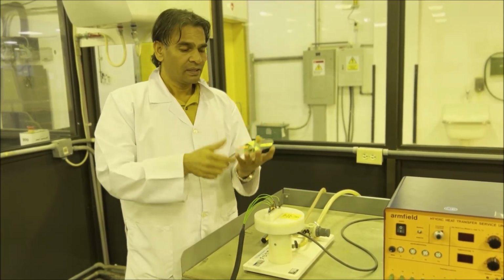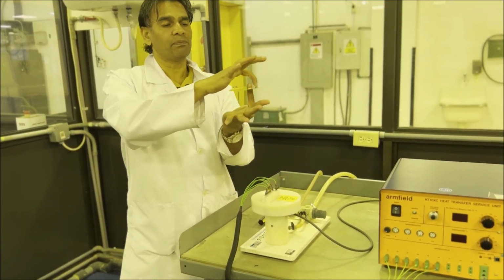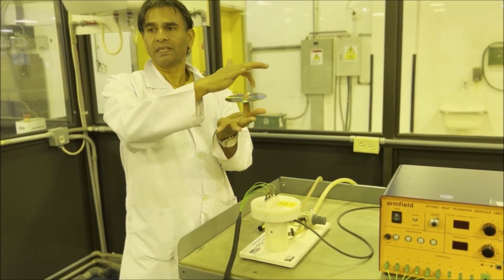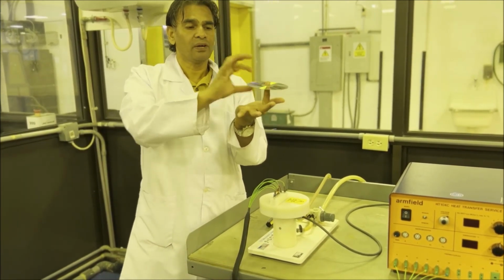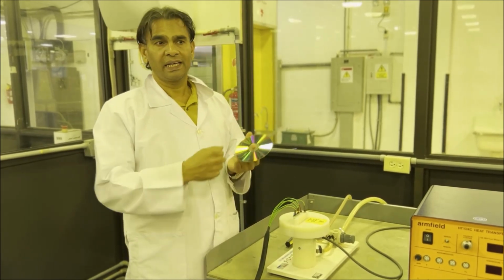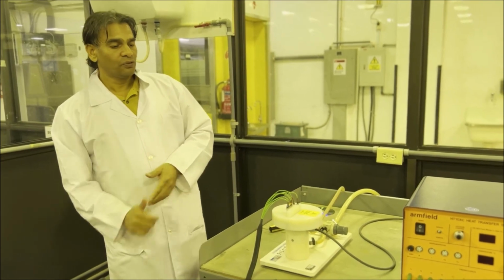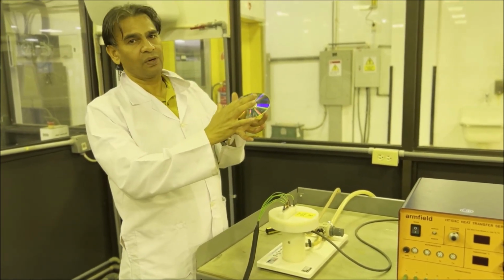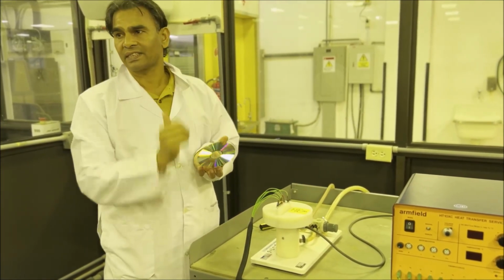So this is a hot heater. Here the temperature is more at radius 1. At radius 2, temperature is decreasing, decreasing. So heat is flowing in the radial direction from all sides. And we will see what is the relation between radius and temperature. In our first objective, we need to find out the temperature at radius R1, R2, R3, R4, R5 and the outer surface.